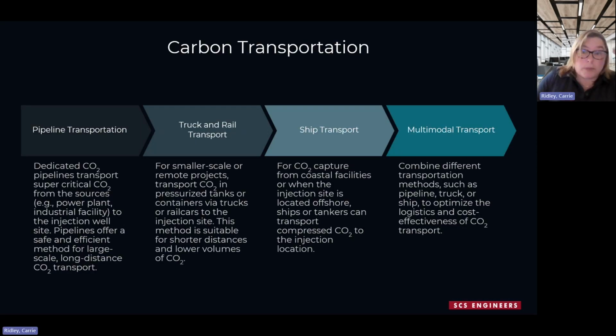So regarding transportation, pipelines are the most efficient way to move CO2 over long distances, and within the footprint of a storage facility between the compression and the wells. The long distance pipelines face significant public opposition. A CO2 pipeline would likely mean new lines that may or may not follow existing right-of-way, and new lines would need to be constructed due to the corrosive nature of CO2, since it wouldn't be able to be used with existing infrastructure.